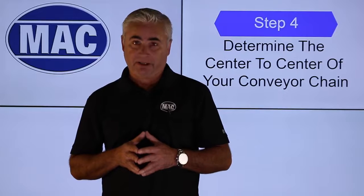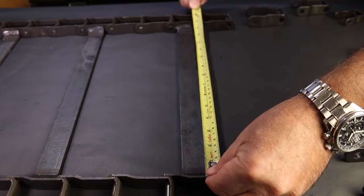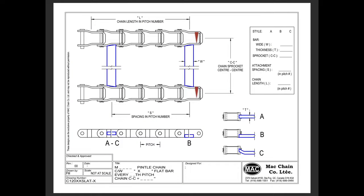Step number 4, a critical step, determine the center to center of your conveyor chain and sprockets. To get your center to center, measure from the narrow end of the link, from the inside of the inside sidebar to the inside of the outside sidebar on the corresponding link.